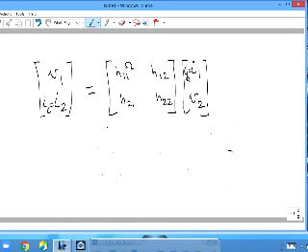Similarly, I2 will be H21 times I1. I is equal to H21 times I, so H21 is dimensionless, plus H22 times V2, so H22 will have units of Siemens or 1 by ohms. Okay. Now in a BJT is where the hybrid parameters are used most of the times.